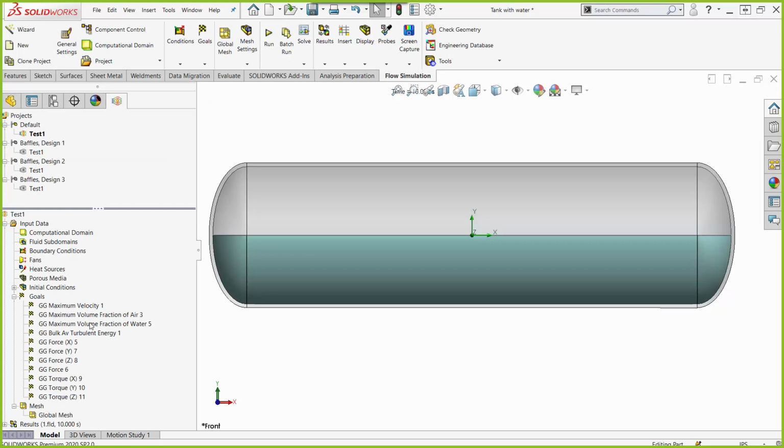You'll see I also have a few things up here at the top. These are more sanity checks. They aren't necessary for the results I want to look at in the end, but while it's solving, I do like to look at these things. It's a personal preference. It's, like I said, a sanity check. So velocity or pressure is one of my ways of sanity checking a free surface or really any analysis I'm running in Flow. And I'm just watching for weird pressures or velocities.